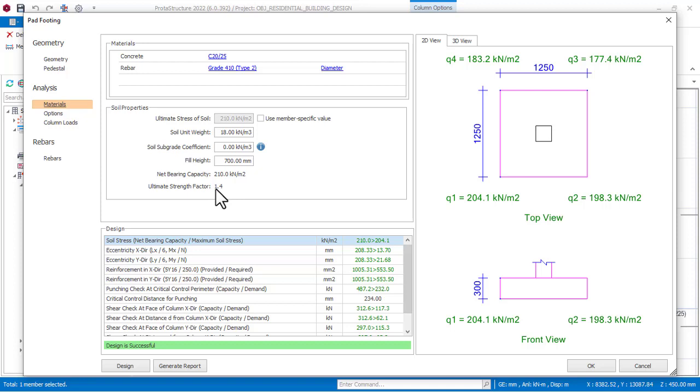If you are using Eurocode, it gives 1.25 as the factor of safety. So if you multiply this value by the bearing capacity, which we have as 150, you get this value here. It is good for you to put your bearing capacity on that first stage and not in this place. Although you can still change it here, I don't advise you to change it.